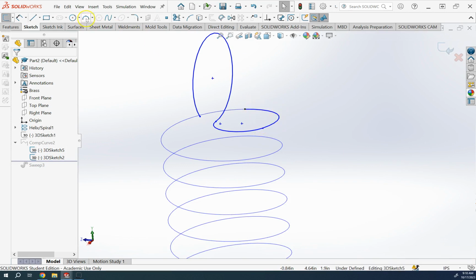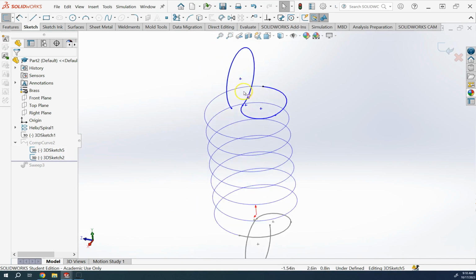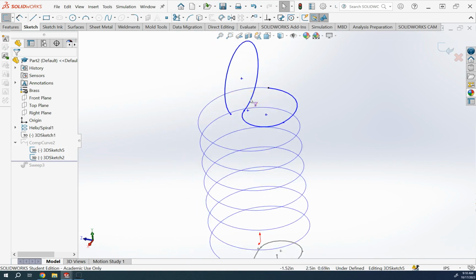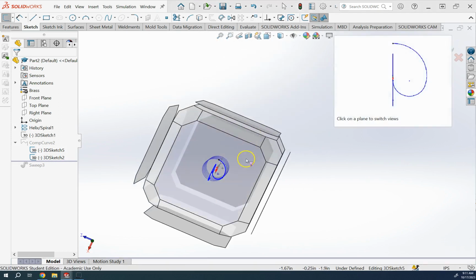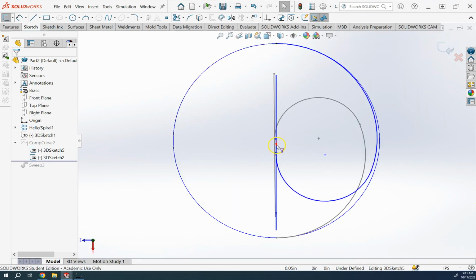It's a 3-point arc from a 3D sketch, followed by another XZ 3-point arc, which is smaller this time. And then I connected it to a 3-point arc, which is this time along the XY plane, along the vertical plane. And if you look from the top, I made sure that they end up at the middle.